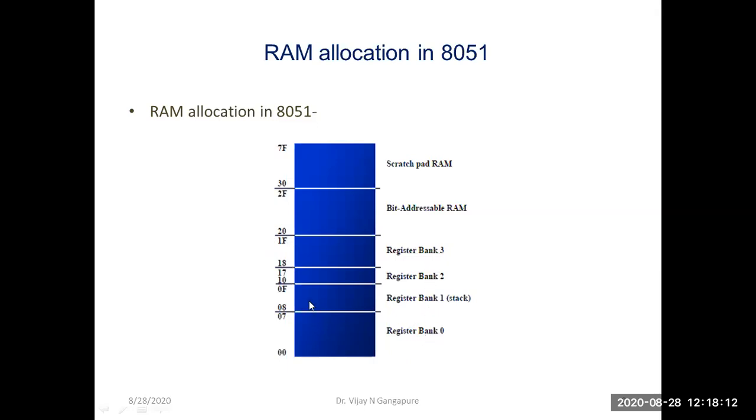Okay, and stack pointer register, as I told you, out of this memory, that is RAM, we can also use it for stack, and we can start using that stack memory starting from address 08, that is from register bank 1.